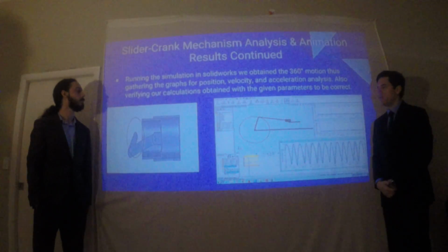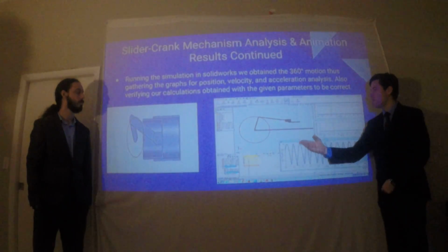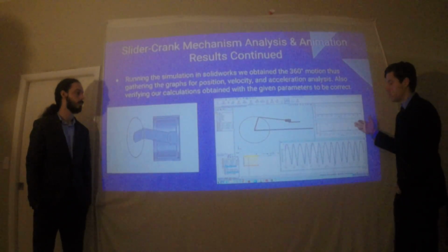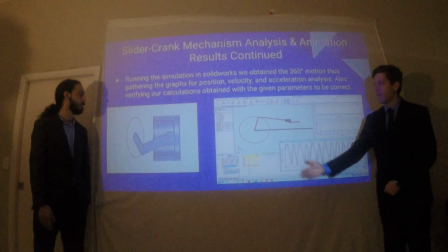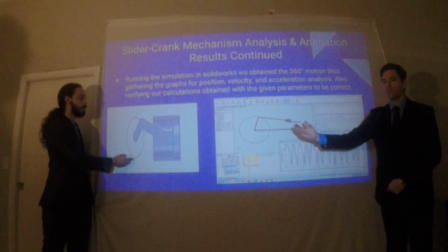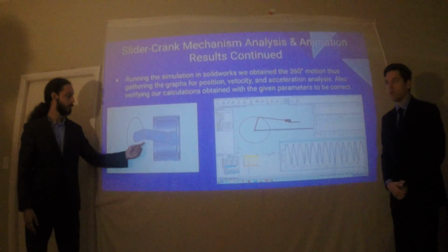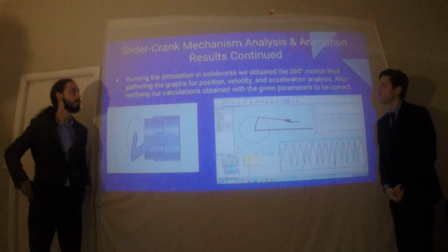After calculating everything on paper, I went ahead and built a simulation in SolidWorks, and I acquired the graphs for the velocity, acceleration, and position of the crank mechanism. I then also designed a piston assembly showing the motion of the piston going through full rotation with no interruption, as well as the slider crank mechanism that we designed.